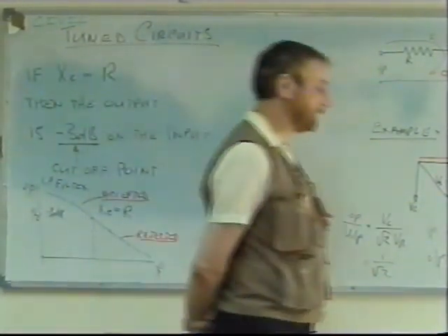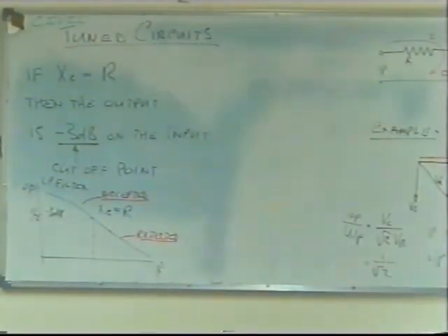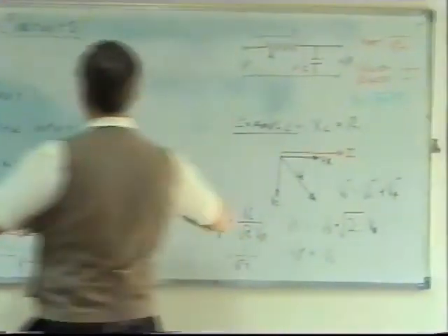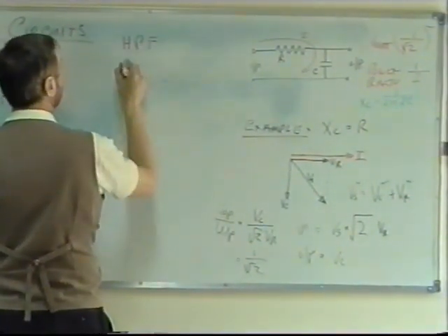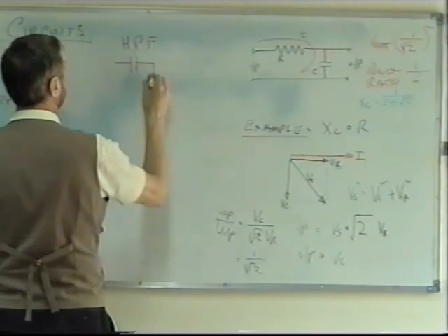And in this example I've shown here, I'm choosing a low-pass filter. If I was to choose a high-pass filter, we would use exactly the same math. There'd be no difference in the way we calculate, except these would be the opposite way around, wouldn't they? In a high-pass filter, it's just that we use capacitor here and resistor here.